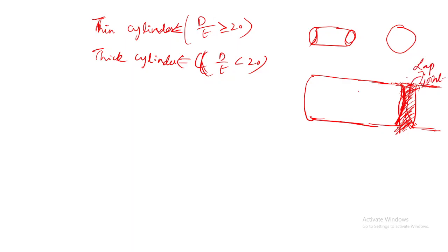In welding we are not getting 100% structural efficiency. There might be some reduction in the structural member compared to the whole solid. So here we are getting the efficiency of the circumferential joint. And with respect to a given diameter, if I want a larger diameter, then I have to join the diameters with a butt joint, and these are termed as longitudinal joints.